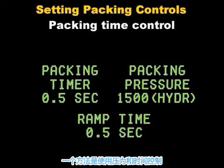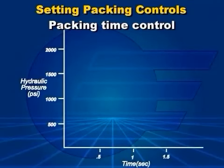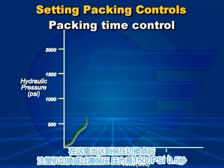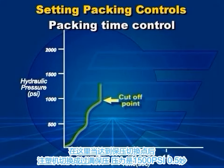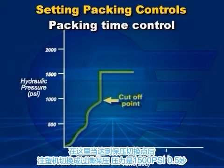One packing method is to use a pressure and a timer setting. In this method, a set pressure is held for a set length of time. This graph illustrates the technique. After the cutoff point is reached, the machine switches to controlling pressure. In this case, it holds 1500 psi, that's hydraulic pressure, for ½ a second.